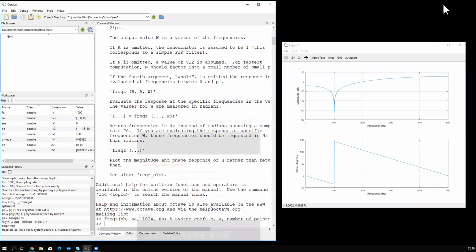And I have the figure somewhere. Okay, yeah, it's nice. It suppresses that 100 Hertz, but it's not a low pass filter. If our information was here, I would say this is a problem. It's actually a high pass filter. We also want to suppress this one. I could add more zeros here. That's one way, but the calculation becomes more and more intense.